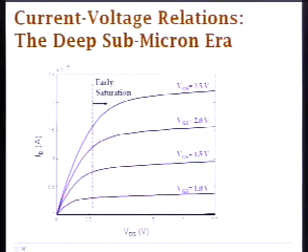So now, going over to the deep submicron era, we introduced this velocity saturation concept, where we basically have early saturation. So we have, for a very small VDS, the horizontal field across the channel reaching some critical value where you have scattering effects and the carriers collide with each other, so you have basically constant speed of your carrier transport, and the speed can no longer increase.